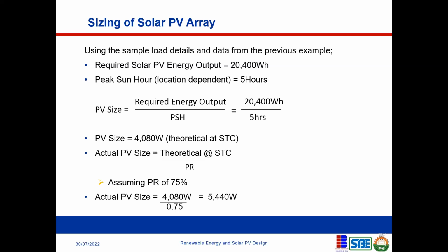And be careful as well. Sometimes when you're going out to buy this equipment, as experts, let us be careful. Buy from authorized dealers. Sometimes somebody will take a PV module of 300 watts and change the label to 400. So if you're doing an installation, please test and be sure of the capacity that you're buying.